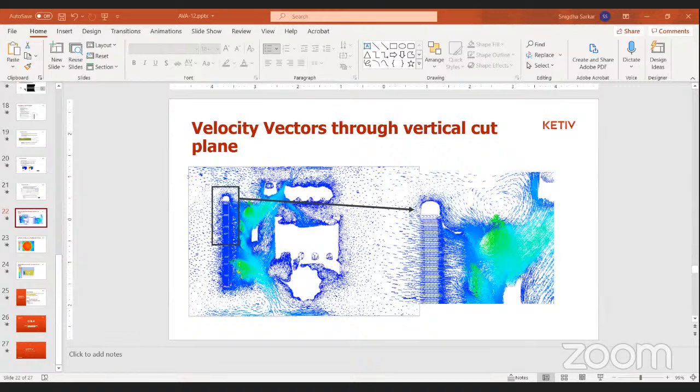Right. So that is what I was trying to illustrate over here, is that depending on your vector contours and your velocity magnitude, you can actually identify the regions in which your airflow is getting recirculated or your airflow is getting pulled back in. So you would need to redesign your machine in such a way so that there isn't any scope for recirculation, or your flow cannot travel back and get sucked into the radiator inlet in this particular example.